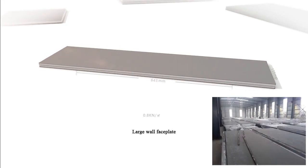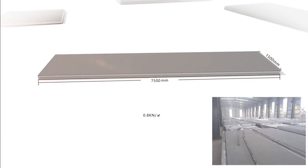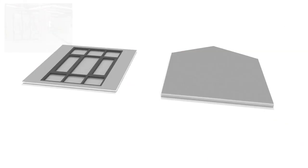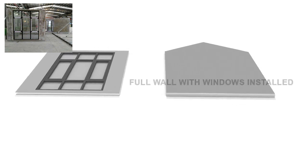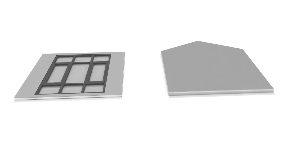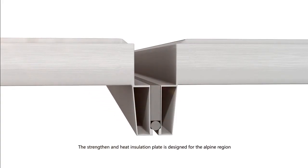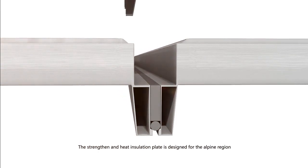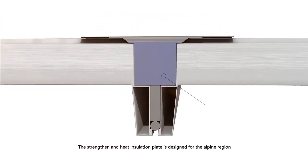Large wall faceplate. Standard board is 1.5 by 6 meters. The allowable load is 0.8 kilonewtons per square meter. The strengthened heat insulation plate is designed for the alpine region. The thermal bridge prevention process is used for the node.